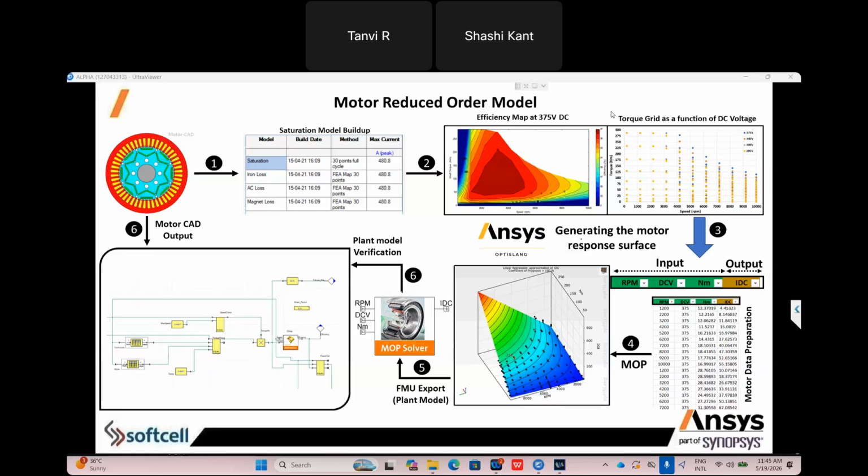And here you can see Ansys optiSLang. optiSLang can be coupled with all the Ansys solutions. I will give you a very easy and simple answer. Let's suppose you did 1,000 iterations using a model or AI model, and you want to understand the response of the 1,000 iterations. Once you couple it, optiSLang can give you the response in terms of efficiency, or whatever you define, such as flight time. It can give you the sensitivity analysis. It can give you the response of the product or simulation as per the requirement.